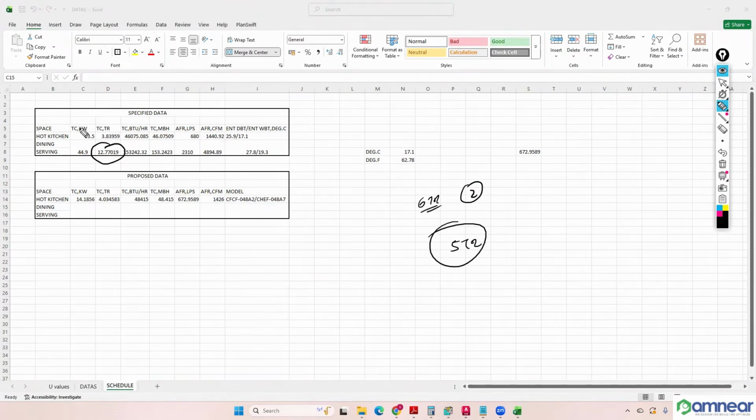Okay, anyhow, so that's why 4 ton 3 equipments you can propose. Minimum 2 equipment is not possible because single equipment, the maximum capacity, most of the manufacturers, it will come 5 ton only. So 2 equipment will come 10 ton, but our requirement is 12 or 12.7. So definitely 3 equipment, if it should match with the supplier. Let me check it.